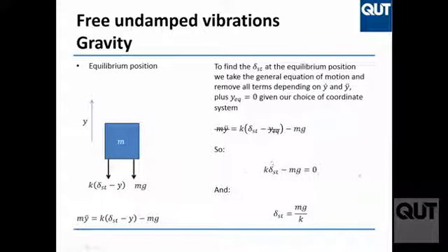That's the equilibrium equation. What does it allow me to find? What do I know? I know g, 9.81. Mass and k, usually I know them. It's the mass of my system and the stiffness of my spring. So I can find how much it actually moves in equilibrium.